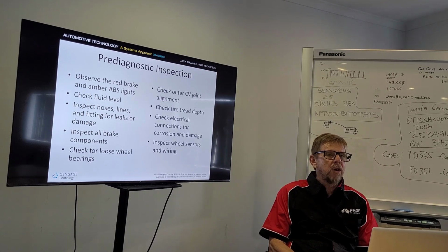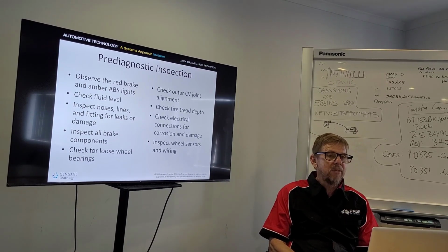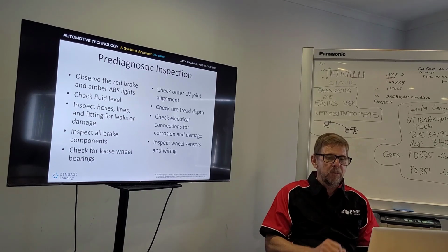So also tyre pressure. Make sure our tyre pressures are even, okay? We'll obviously look at all the electrical wiring and connections, look for damage or corrosion. And inspect the actual wheel speed sensors and wiring at those sensors too, okay?